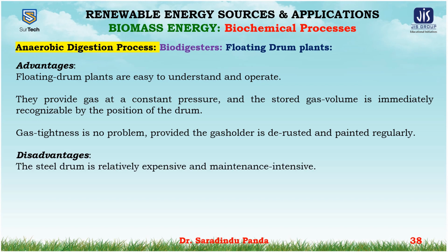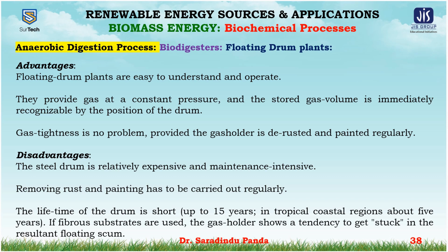But there are some disadvantages also. The steel drum is relatively expensive and maintenance intensive. Removing rust and painting has to be carried out regularly. The lifetime of the drum is short, up to 15 years. In the tropical coastal regions, about 5 years. If fibrous substrates are used, the gas holder shows a tendency to get stuck in the resultant floating.